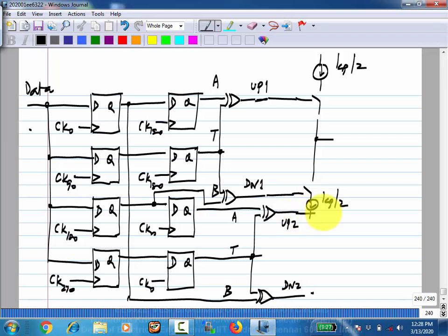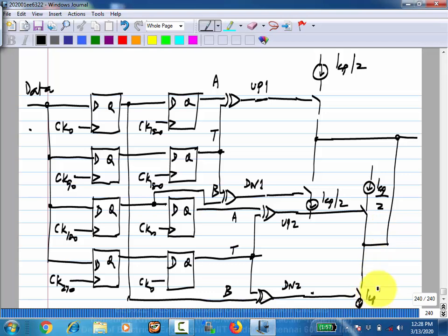And then similarly, these should be, this is one possible implementation to do this at half rate, and then you can just connect these things in parallel, okay. This is fine. Just imagine that your clock is lagging the data, then you are getting up signals in both up 1 and down 1, and then you will get a constant current of ICP, okay, which is what you were getting earlier also. Is this okay? So this will be exactly the same, but there are many other options.